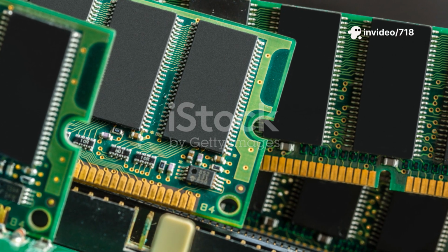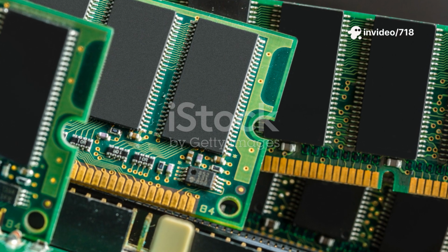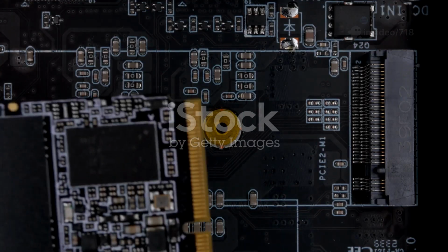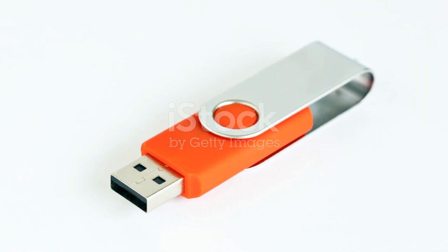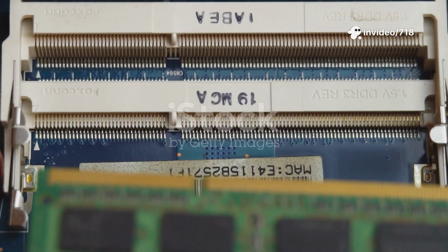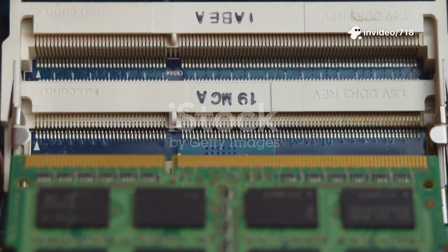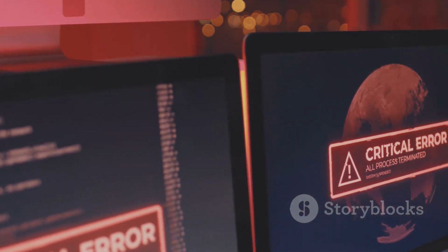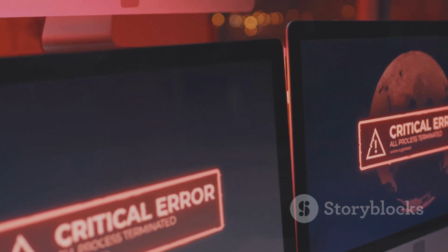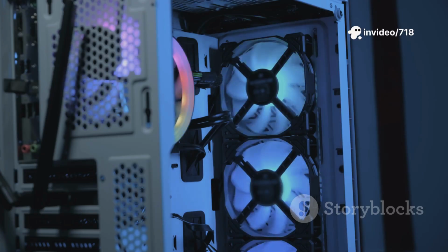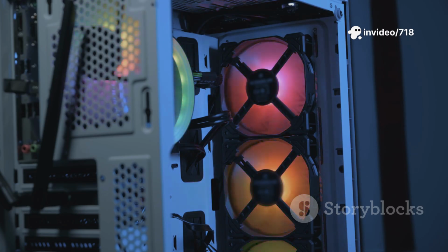Now let's shift our comparison to another type of memory you use every single day: flash memory. This is the technology inside your solid-state drive, your USB pen drive, and the storage in your smartphone. The biggest and most fundamental difference between DRAM and flash is volatility. As we know, DRAM is volatile memory. The moment you cut the power, the refresh cycle stops, the capacitors leak their charge, and poof, all the data is gone. It's a temporary workspace, designed to be active only when the computer is on.